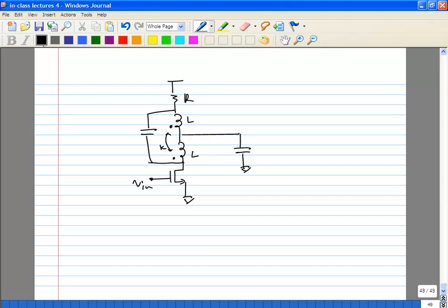That I think is too much for this class. To explain why that happens may be a little bit too much, but we'll just assume that it does help. So you can put a capacitance CB across this. This structure is called the bridged T-coil. It's a very popular technique for bandwidth extension. You can see this one is called a T-coil and it's bridged with a capacitance CB.